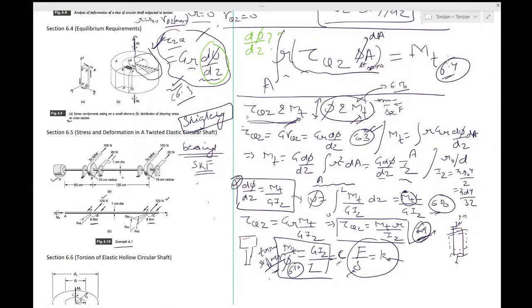Okay, so each pulley is supported by a pair of immediately adjacent bearings. We make the idealization that the 120 Newton transverse force is balanced by the bearing reactions in such a way that there is negligible shear force and bending moment transmitted beyond the bearings. So that is one of the purposes of this bearing.